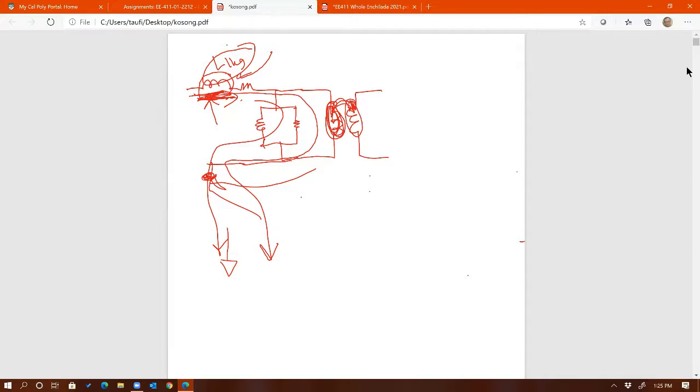By keep increasing this voltage, right? If this voltage is high enough, then electrons will jump through the air. And if you're not careful, this leakage inductance could be big enough that it could damage this MOSFET or this switch, right?